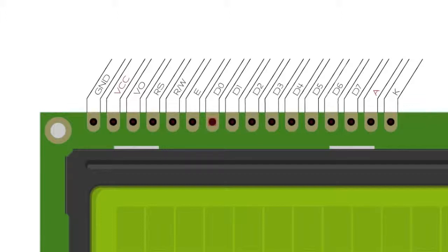However, the Arduino Liquid Crystal library is quite clever in the way it handles things. You can tie the RW pin straight to ground, which permanently puts the LCD in write mode and introduces a long enough delay for the LCD to become free. This is less efficient code, but it saves on a precious I/O pin, and you wouldn't notice the extra time taken anyway. Then comes the E or enable pin. You can think of this as sort of a light switch for the LCD. When you flash this pin high and then low again, the LCD can see the state of the other pins and execute the right command.